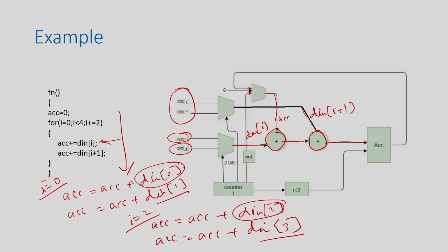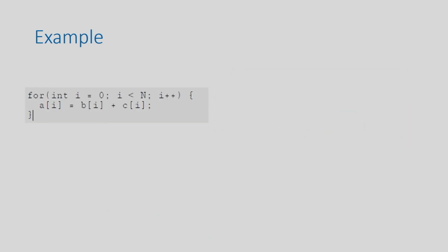Okay. So, this is what I tried to show, how we should multiplex these arrays, and I am assuming this array is basically mapped to registers. Okay. They are all available in parallel. You can understand this partial unroll depends on your resource availability. You should decide your unroll factor and it will improve the performance, without much increment of the resource requirement.